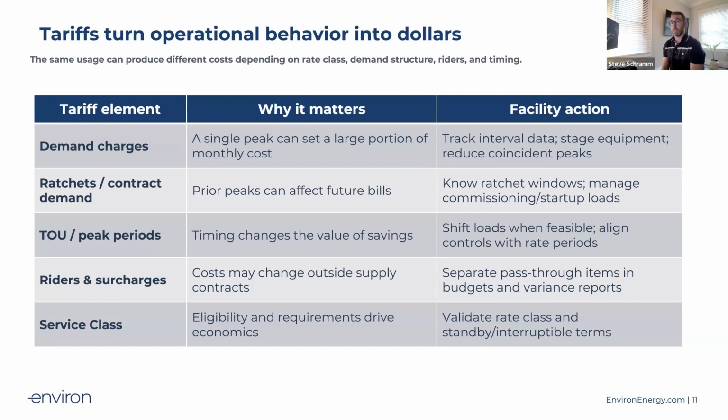The first being demand charges. Depending on which ISO you're in, you would have something called a coincident peak, commonly referred to as a CP event. In ISO New England, it's a bit different than ISO New York, then different than PJM. Managing your single peak is when your hospital consumes the most amount of power. When we call it a coincident peak, it's when your hospital consumes the most amount of power when the grid is at its most strained, or the most consumption is being applied to the grid.